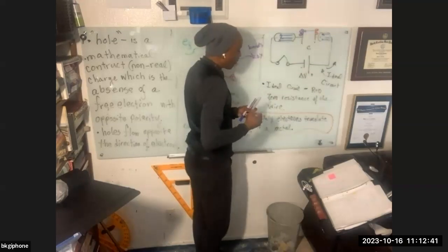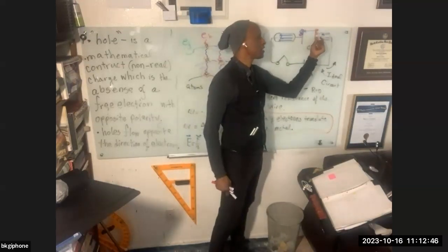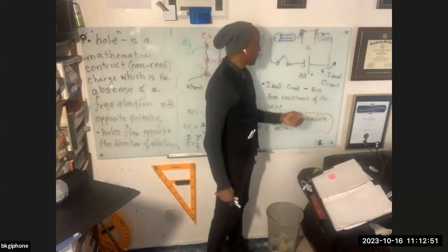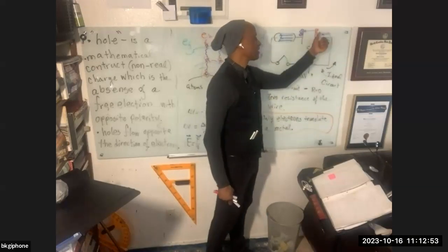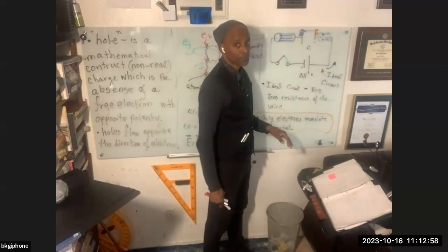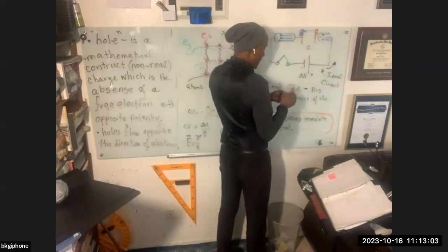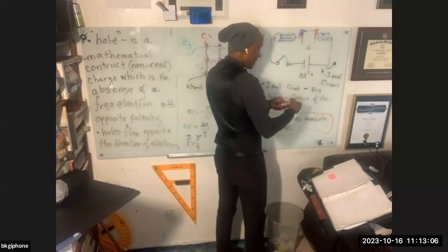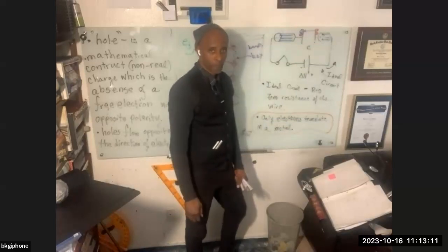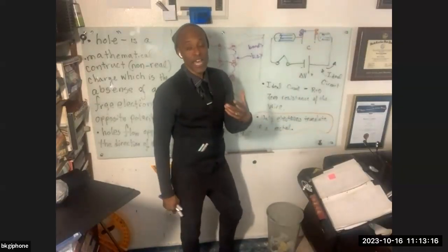And also a little bit more work to pull an electron off because this plate is now positively charged, so the electron doesn't really want to come because it's attracted to that plate, but it's attracted more to the battery than to the capacitor while the capacitor is charging, because the battery has a larger voltage. And now you also begin to see a voltage on the capacitor, right? Because it now has a positive and negative plate. So there's a delta V that's increasing as the capacitor charges up. So we've got three things increasing on the capacitor as it charges up.